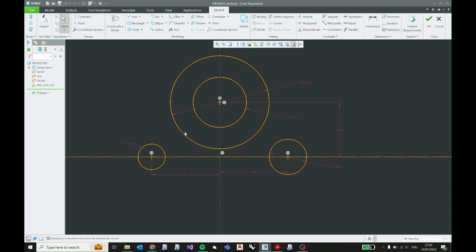These are not moving. The whole model is symmetrical about this axis, so we don't really need the bottom half of these circles. You can keep it there, but I'm gonna take it off, because in the end I'm gonna use a mirror command, select the whole thing, and mirror it across this axis. So I don't want to double this circle when I mirror it. You'll see in the end when I use the mirror command. Perfect.